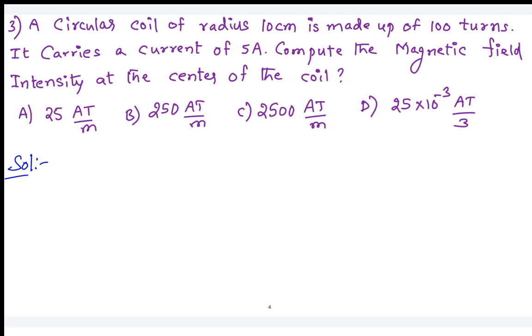So first, what is the magnetic field intensity due to a circular coil? Let us see, I is the current flowing through that, and at the center, what is the magnetic field intensity formula? You remember? Just before the Helmholtz coil, I have discussed what will be the magnetic field intensity at the center. I by 2R. Correct. So this I by 2R is valid by assuming there is only one turn. Right now, in this case, how many windings are given? N number of turns. So the magnetic field will be N, right?